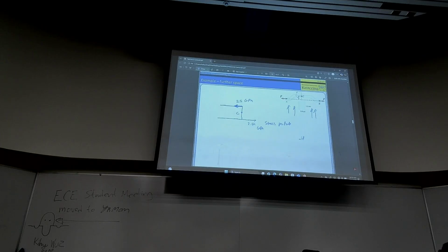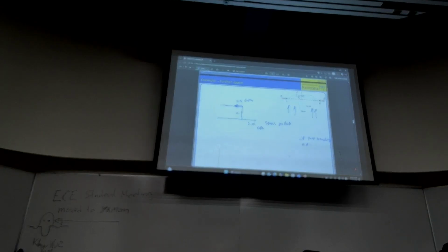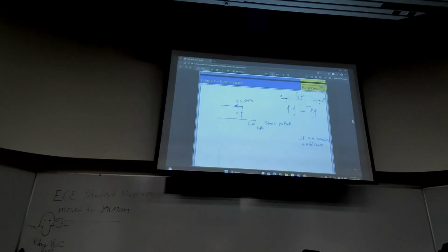If force is axial, that means no offset. If it's axial, we know that there is no bending, but I wanted to talk about pure bending. If pure bending, it could arise with M alone, the moment alone, then we know that the neutral axis, NA, occurs at the centroid of the cross section.